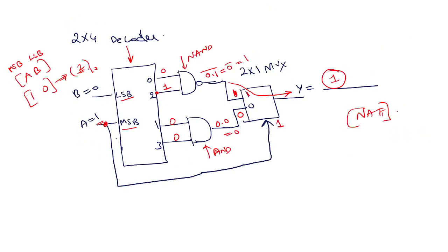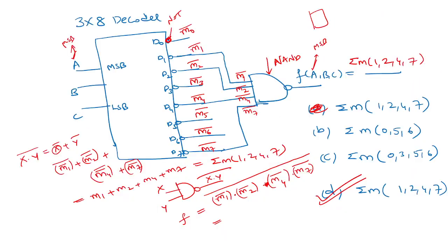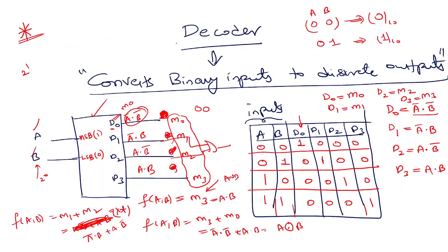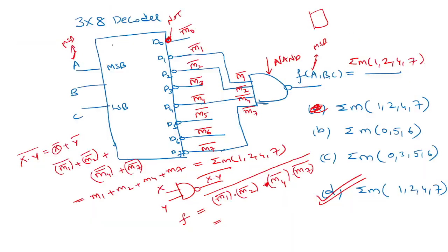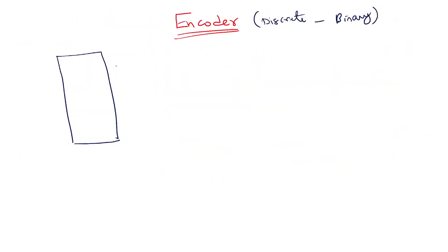So you have a decoder here. If I have to configure it, I should write it as 2 by 4, 3 by 8. It means that many combinations are possible. Like that, if I have n inputs, I have 2 power n combinations possible at the output side. Similarly, for an encoder it is the opposite, 2 power n by 1. It has to do exactly the opposite of the decoder. Right? Let's say I'll take 4 by 2.